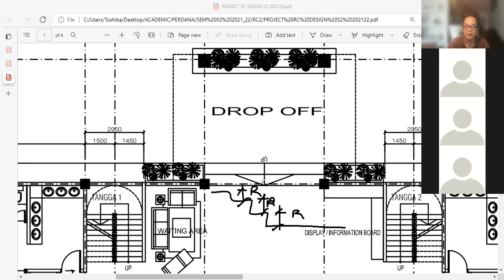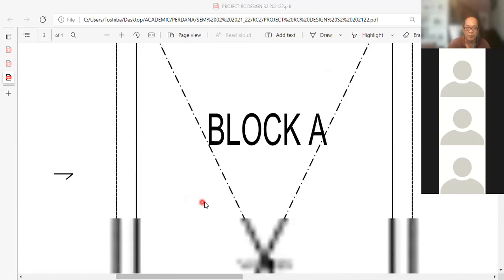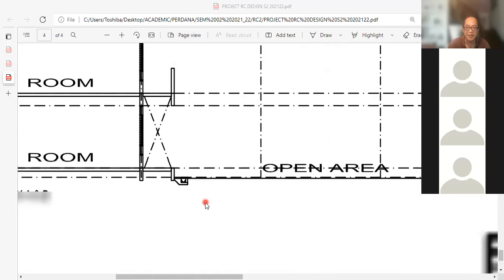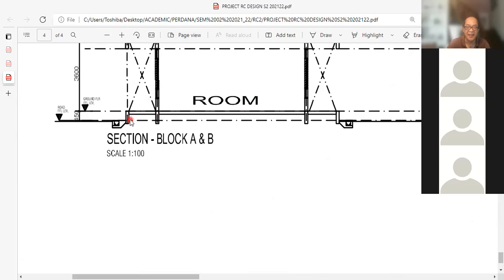Okay, just by looking at this, we can see that the ground slab of the building is raised up by approximately 450 mm. Clear? Okay. So again, back to the sketch that we have looked at earlier. And one more thing, since it is to be a raised condition ataupun a raised ground slab, then if we were to have a look at this particular condition di sini, okay, then we would have something like a ground slab, kemudian ground beam, suspended ground slab and ground beam.